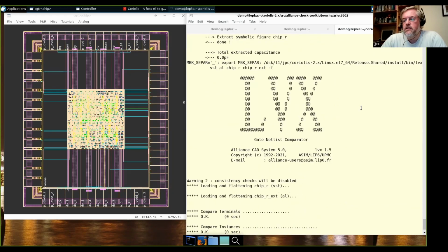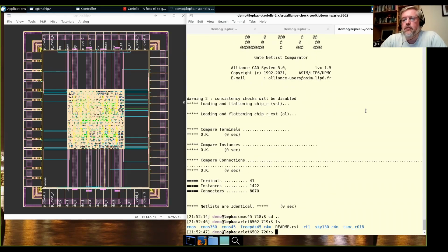And moreover, I didn't present it in this presentation, but you also have TAS and YAGL, which are tools made by our lab, which from the netlist of transistors, at transistor level, the SPICE netlist, can recreate the logical function. For example, if you have a NAND, it's able to tell you that, okay, those transistors are making a NAND logical function.